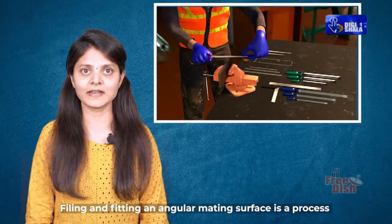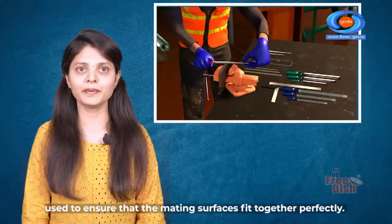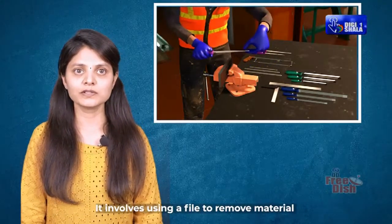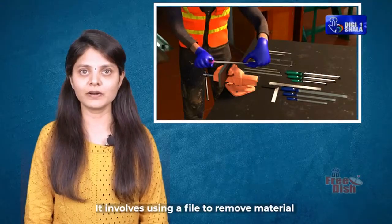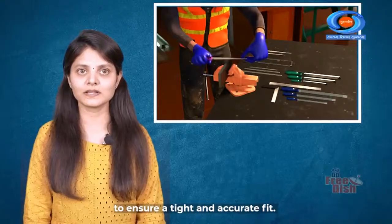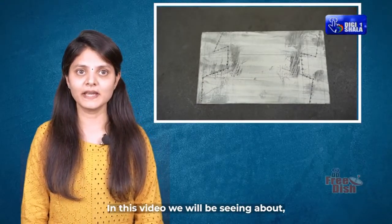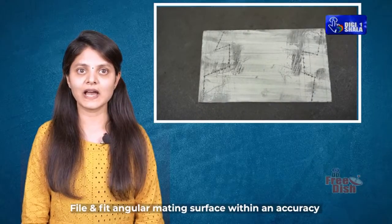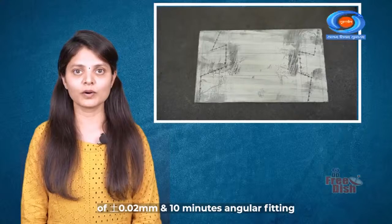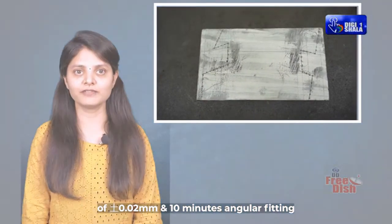Filing and fitting an angular mating surface is a process used to ensure that the mating surfaces fit together perfectly. It involves using a file to remove material from the surface and then fitting the surfaces together to ensure a tight and accurate fit. In this video, we will be seeing about filing and fitting angular mating surface within an accuracy of plus or minus 0.02 mm and 10 minutes angular fitting.